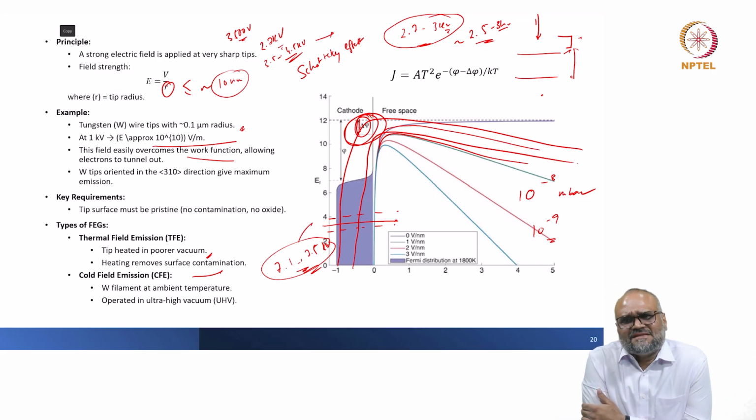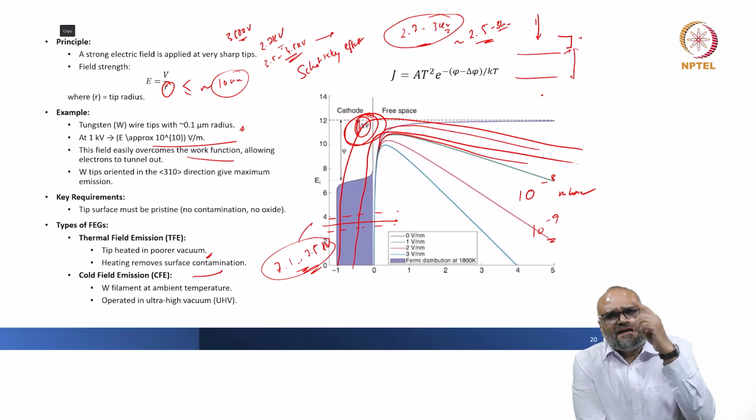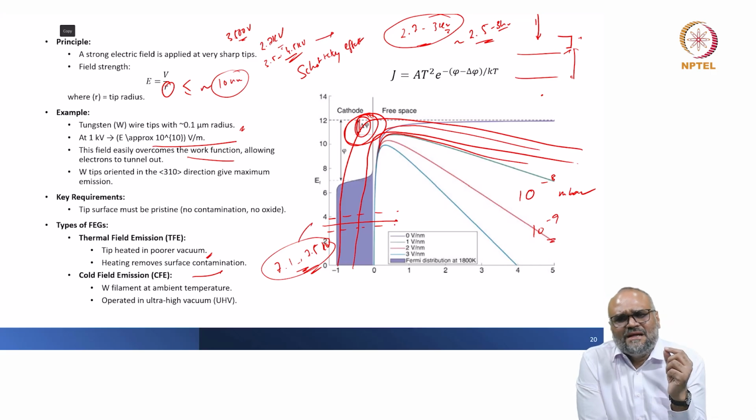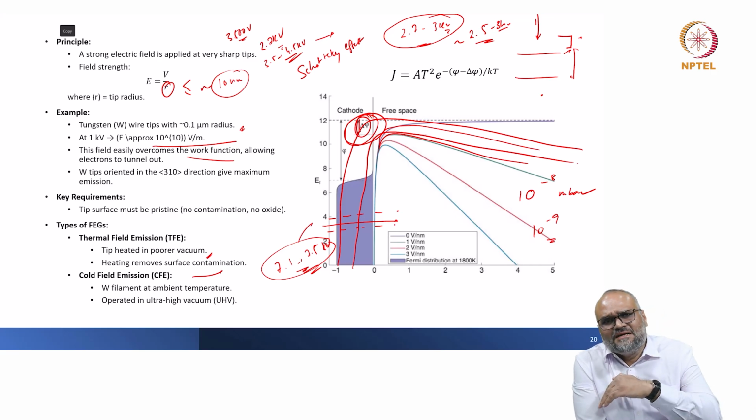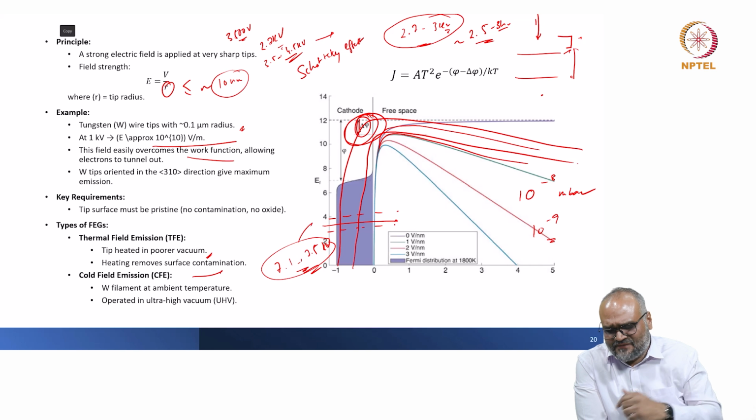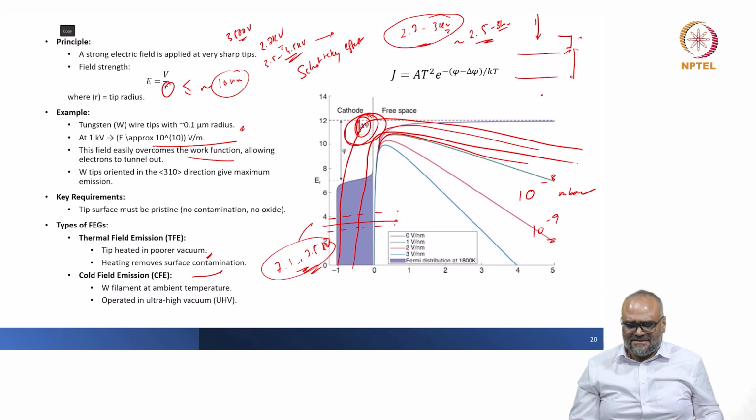There have been cases where cold field emitters have run significantly beyond 5 years or even 7 years, and it runs fine. That is because every time an oxide layer is formed and the vacuum is also maintained very well, you are removing the top oxide layer by flashing. So that is about the lifetimes of field emitters and so on.